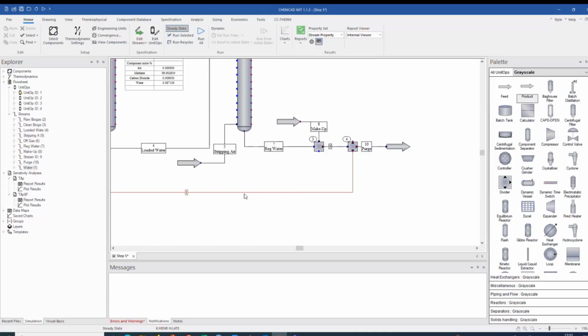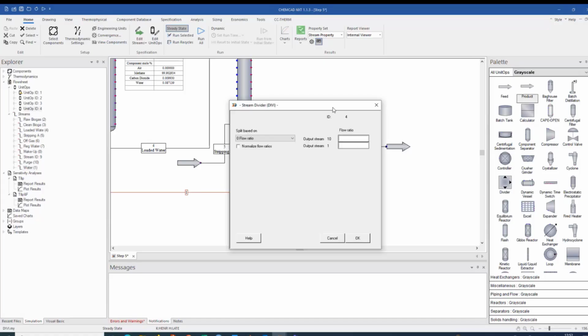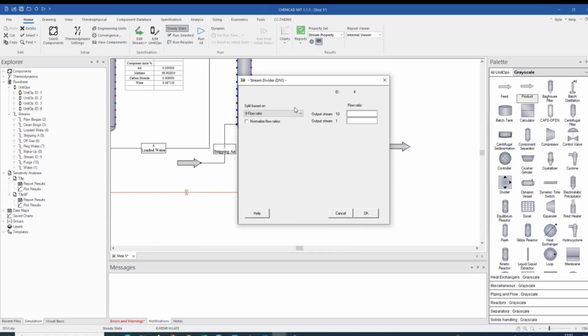And we can specify which size it should have, which flow rate. So here I don't want to use the flow ratio, but I would like to use the flow units defined below. So standard cubic meters liquid per hour. And stream 1, we've seen like 110 cubic meters per hour works fine for our process. So in this unit, we specify our degree of freedom, which is the water flow rate.